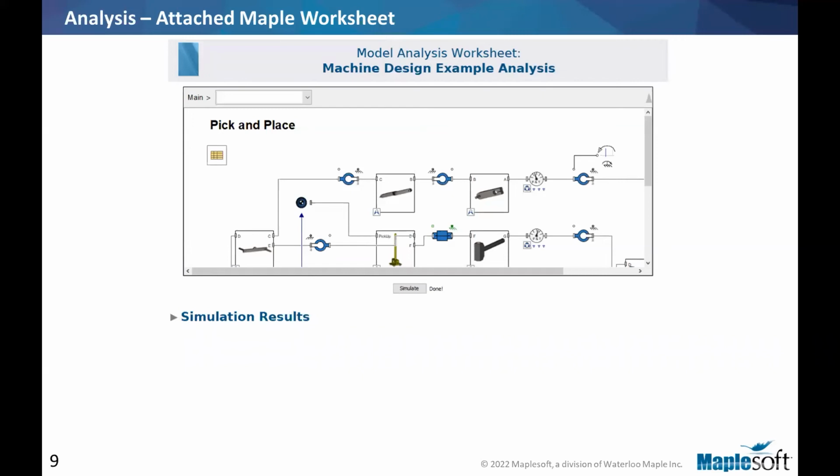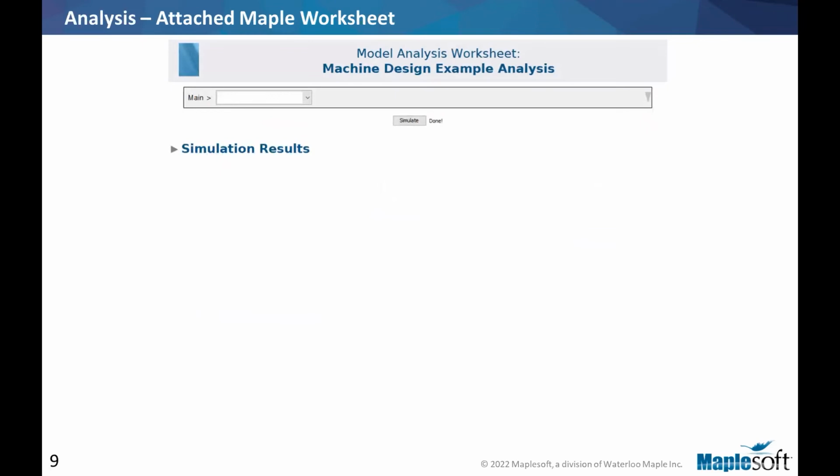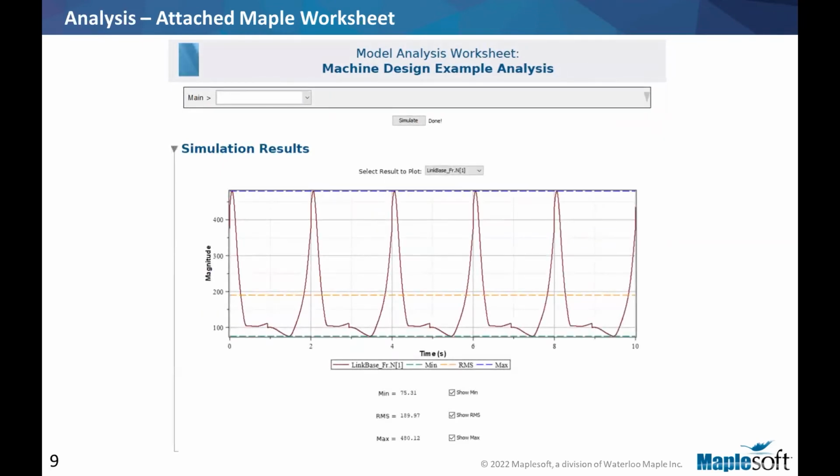And then you can actually do things programmatically. Things like running a simulation, changing parameters, collecting results, all the things you can do in MapleSim, you can now do programmatically, in addition to having all the packages that you would normally have in Maple for processing. So in this example, I can see my model. I have a button that I've programmed to simulate. I run it, and then I can go to my simulation results section. So I collapse one area, expand another.